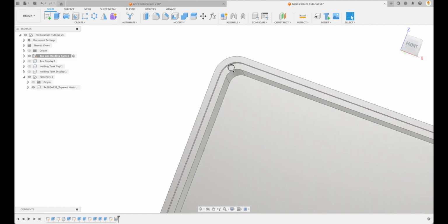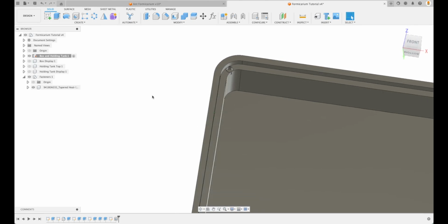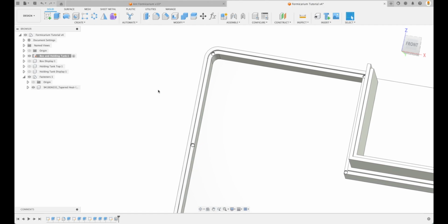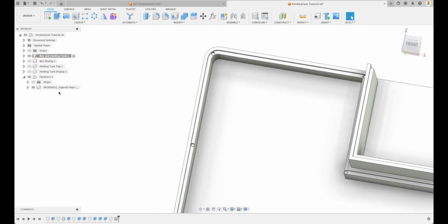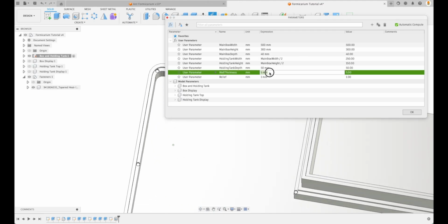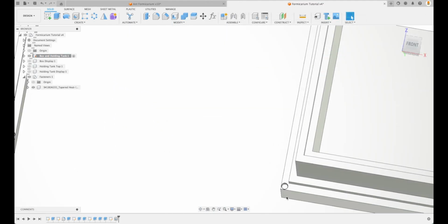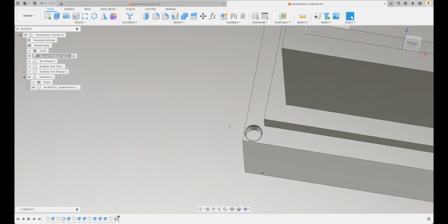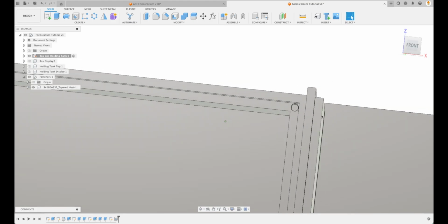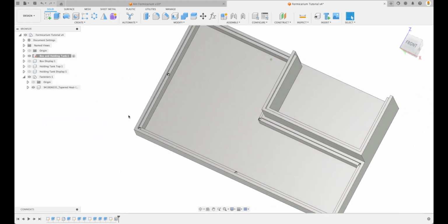But our holes are a little bit too big for this wall thickness, so we could also make the wall thickness just a little bit bigger to save the time from trying to insert all those and finding a different insert. I'm just going to make the wall thickness 6 mils, and this should solve it. There we go. It's not breaking through the side over there. I think this is fine over here. Yeah, that's all looking really good. Okay, so we've got all of the hole positions.